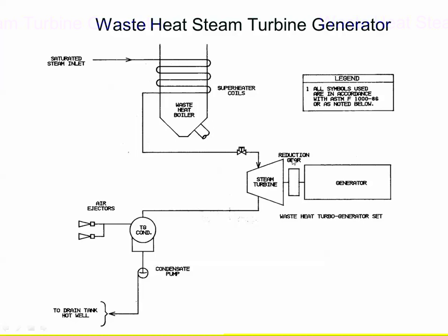On some of the ships I've been on with this system, your oil-fired boiler is shut down out at sea, plus your auxiliary diesel engines, your generators, are shut down, and you're strictly running on this steam turbine waste heat. So think about that, even on the Bear, how much money we could save if out at sea all your electricity and all your steam heating was produced from waste heat.